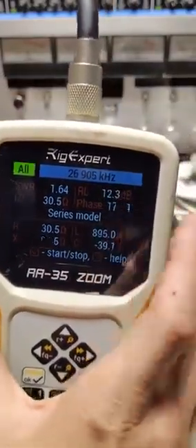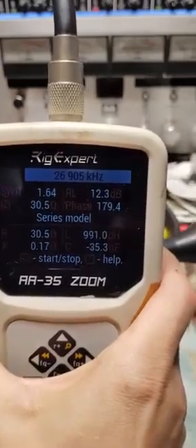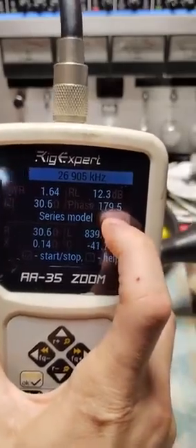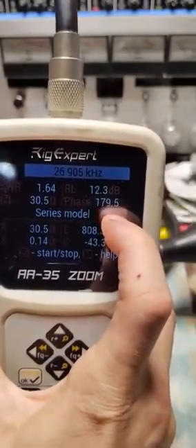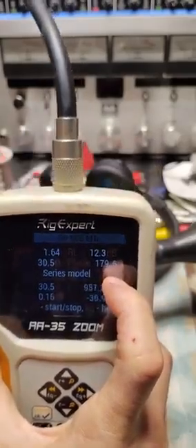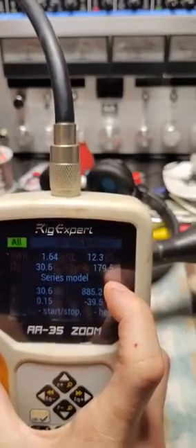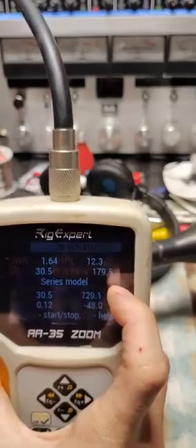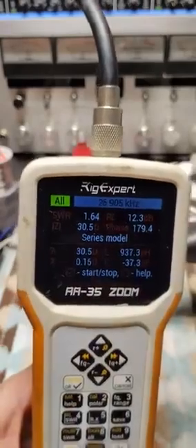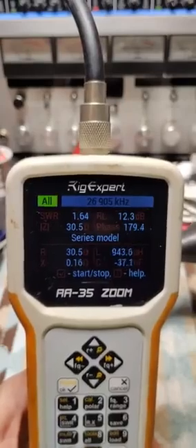Whenever you're tuning an antenna, you should use a tuned half wavelength piece of cable that presents a 180 degree phase angle. And what that does, it gives the reciprocal, it's a mirror. It's not the impedance, it's the mirrored load of the feed point. 180 degrees, okay, that's what you want.